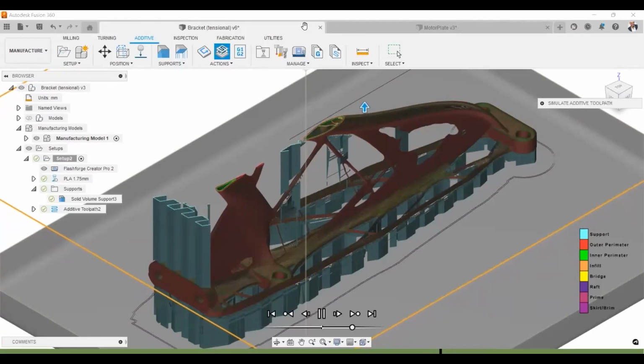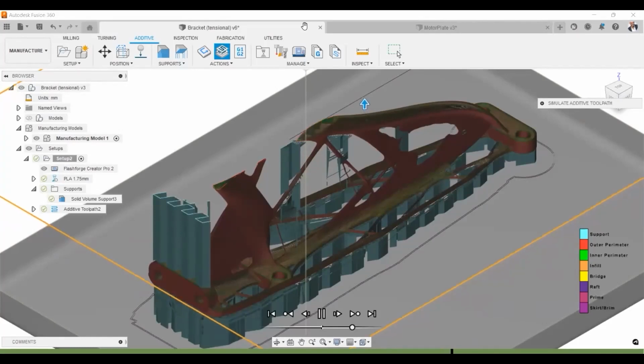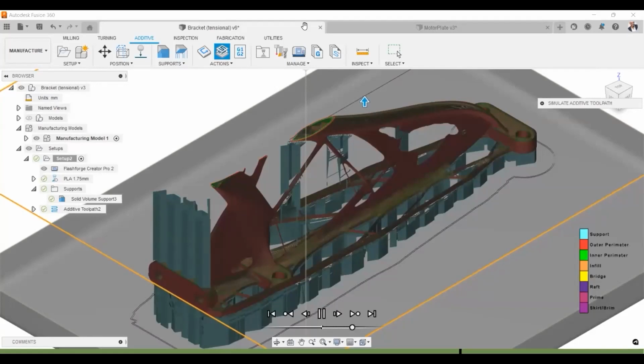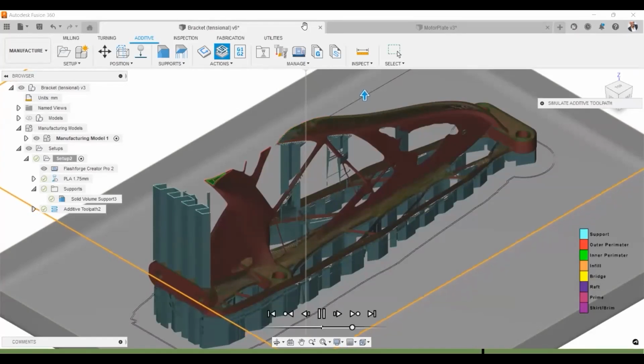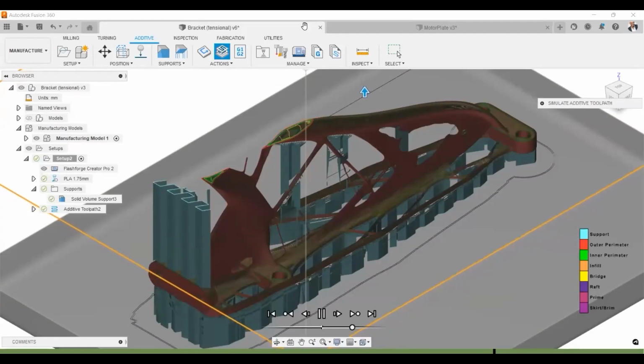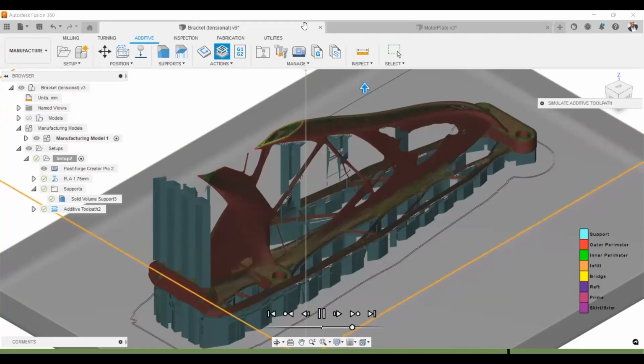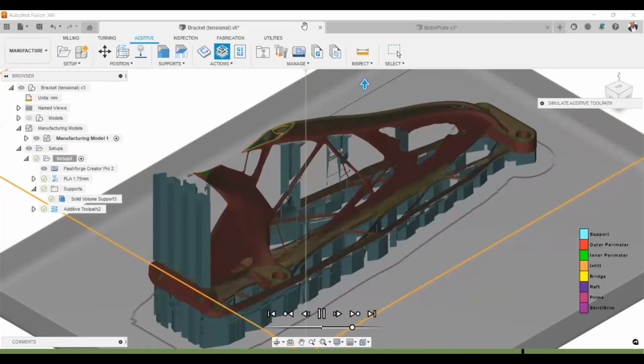Today we have 3D printed molds, metal 3D printed molds that you can print. You design your product, 3D print, and yes, you want to get into the injection mold, but instead of going through machining the mold, you can actually get your mold in one or two weeks, print it, and then ship it into the injection molding machine where it can produce thousands of copies. So 3D printing or additive manufacturing can come into different points of your process.